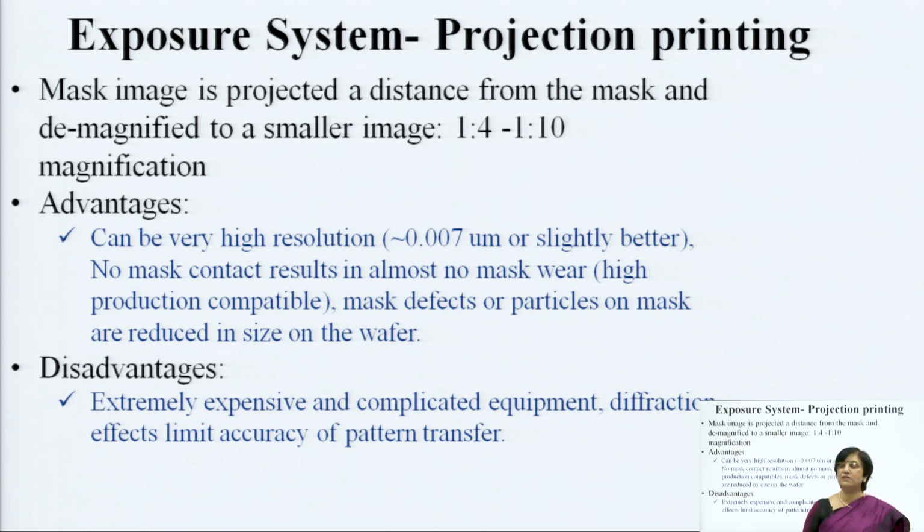So, this is the best method being used. You have very high resolution, up to 0.007 micrometer, or even better than that. So, scaling issues can also be addressed. You do not have contact with the mask, so mask life is saved, and mask defects and other problems are also reduced. You do not have any impact of dust, because the pattern is projected directly through a distance.